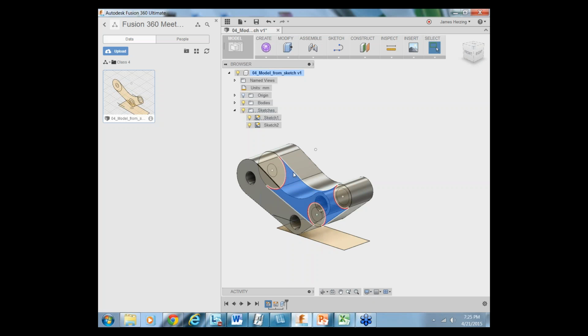So when you extrude the sketch, it automatically hides the sketch that you just used. I'm not sure why. So if you click on the little drop-down button next to sketch, you can then turn the light bulb back on to show that profile if you want to. But every time you use it, it's going to re-hide it from you. Like you just consumed it, but it's still there.